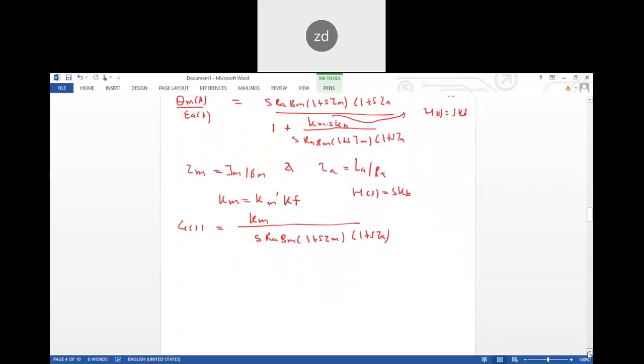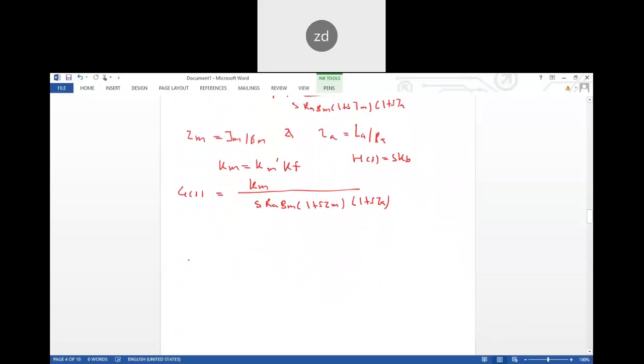Now you can reduce this equation into the closed loop form, wherein the input is Ea, going into a summation block acting as a comparator. From there you have the first block, the torque constant term, which can be expressed as Km over s Bm (1 plus sTm).